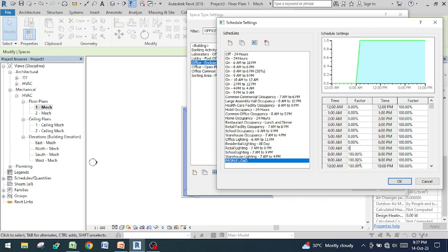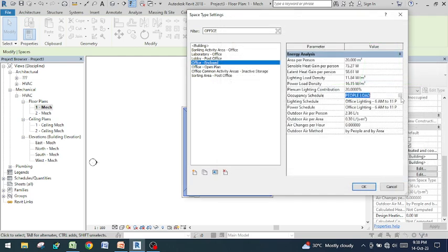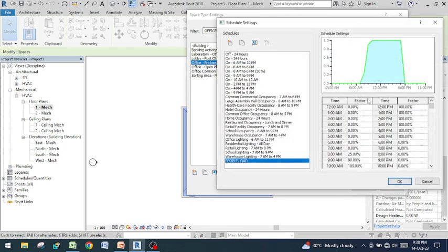At 8 am, I simply make it 25% of people coming at 8 am, and 90% of people come at 9 am. After that, up to 5 pm, I can set the value to 100%. After 6 pm, the people will go home, so the percentage will change from 100 to 0 percent. Here you can find the graphical report, the analysis report as a graph.